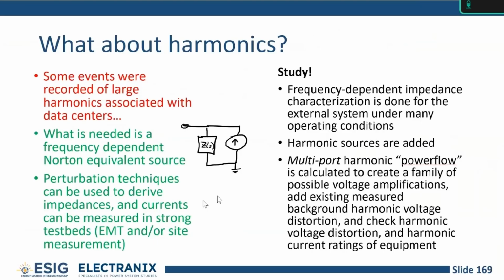Somehow the load was able to overcome that in their lab. So then you do frequency-dependent characterization for the external system. So you do frequency scans of the external system, you add your harmonic sources, and then we do a multi-port harmonic power flow. So this is sort of a very special study. You can calculate also some representation of the background harmonics. You can use a distributed background harmonic model, put it into your power flow, and calculate whether there's going to be a harmonic amplification problem or not. So it's a sort of specialist study, something to think about though.